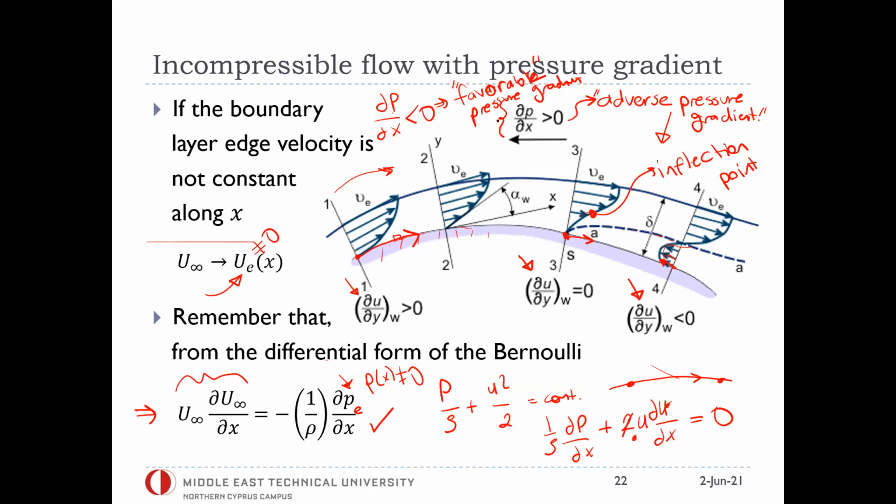Many of the problems we deal with in aerospace engineering, over aircraft wings, helicopter blades, and compressor blades in engines, we always deal with adverse pressure gradient. I said turbine blades, sorry, compressor blades. In a gas turbine engine, inside the jet engine, we have turbine blades. On the turbine blades, we almost all the time have a favorable pressure gradient. I don't know if you discussed this in the propulsion classes, but if not, you will probably see that detail next semester in propulsion too.